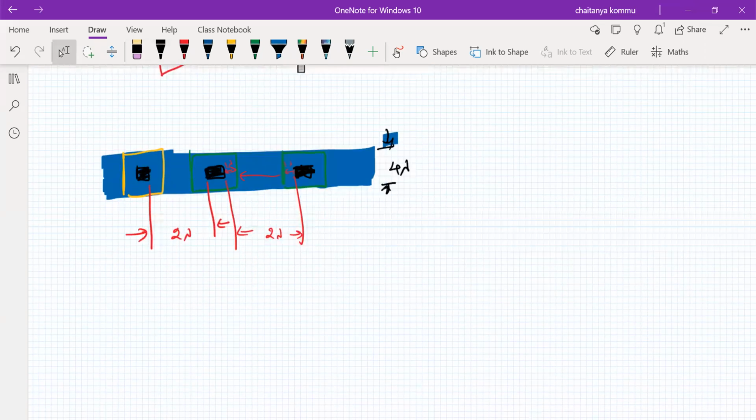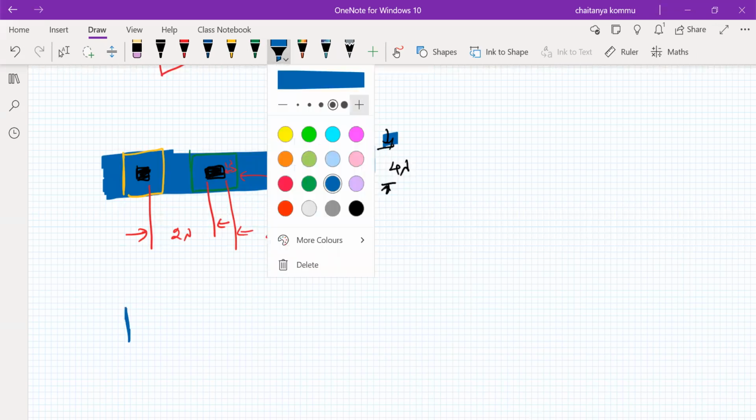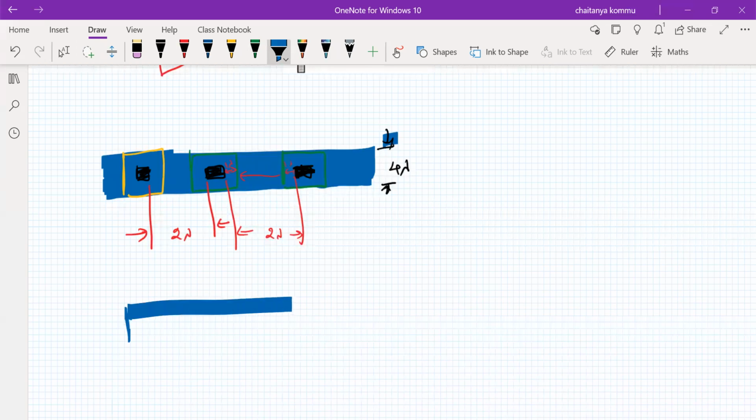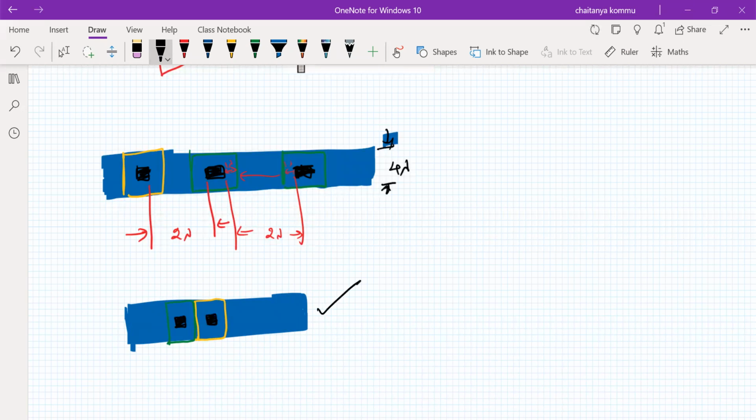We can place it very near to each other. So what it means is that we have to consider it in this way. The point is that I have a contact cut here, and one contact here. So I have to connect another contact here also, for example. So the overlapped regions are very near to each other. Therefore, we have to provide a contact cut here. Here we have another contact cut. Therefore, it's possible. This is also right.